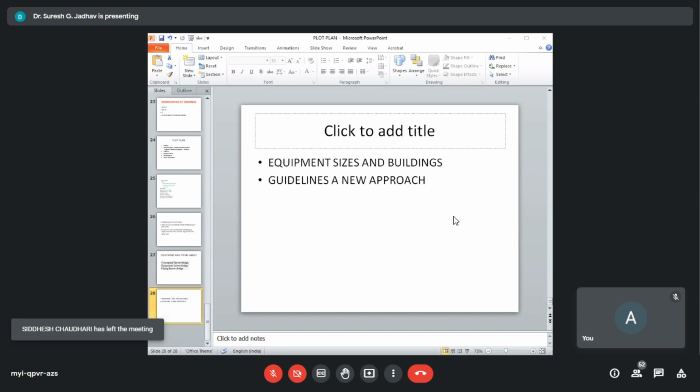Identify the group of equipment that forms a subsystem within the unit, and the components within the subsystem are to be arranged to have the most economical piping, and the whole subsystem is to be placed within the unit to have the most economic interconnections.